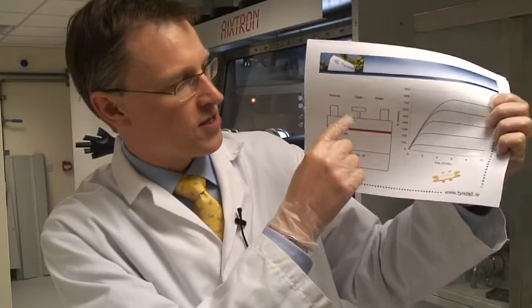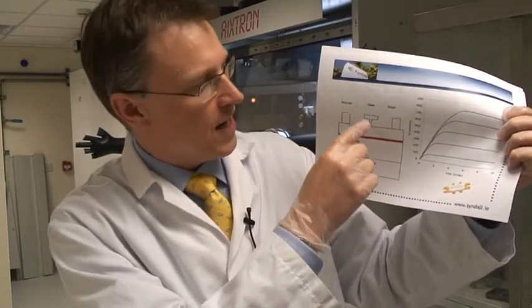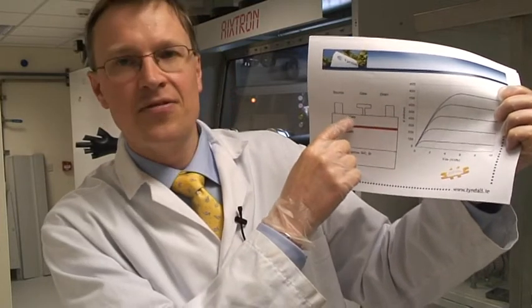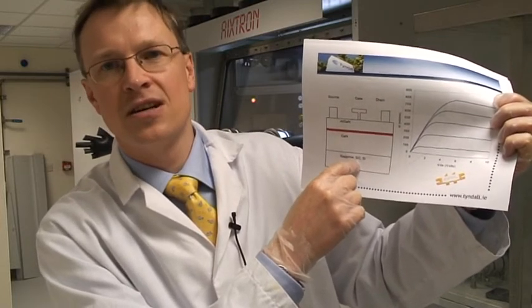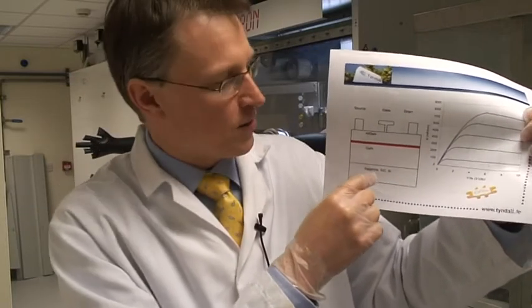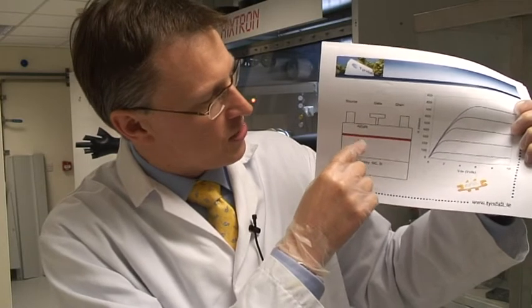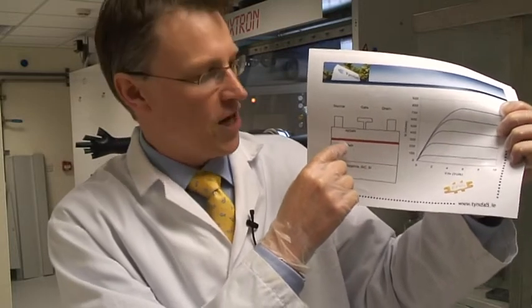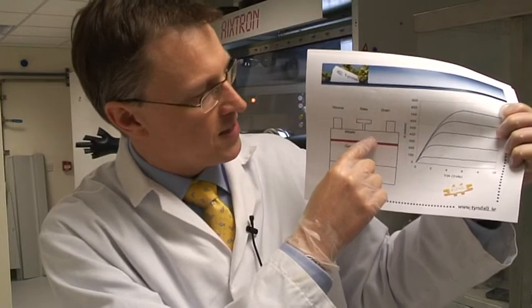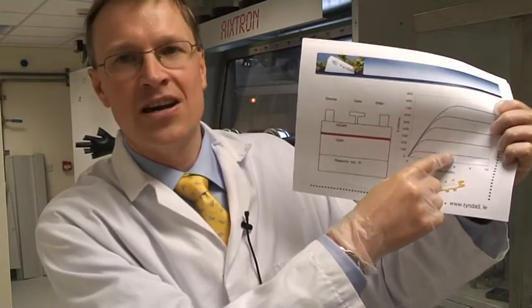This shows you a typical gallium nitride electronic device. We basically form a source and a drain contact on the surface, which are ohmic, and we put a gate in between. There's a thin layer of aluminium gallium nitride on top of a gallium nitride layer, which is on the sapphire, silicon carbide or silicon substrate. We can choose the substrate according to the application. They each have merits for different applications. At the interface between the aluminium gallium nitride and gallium nitride, we form a so-called two-dimensional electron gas. This allows us to have a channel that allows conduction between the source and drain. Applying a voltage to the gate allows the channel to be depleted, allowing us to get a transistor characteristic as shown on this side. These show the two key applications for gallium nitride in electronic and optoelectronics.